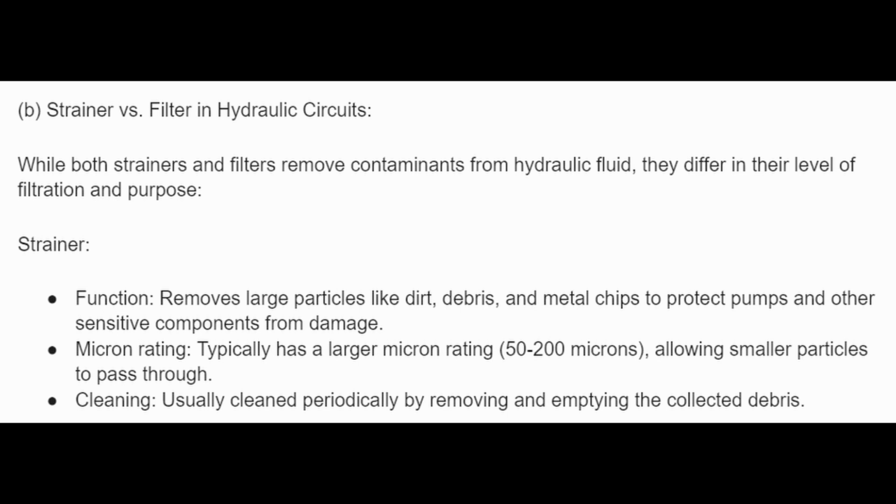B. Strainer versus filter in hydraulic circuits. While both strainers and filters remove contaminants from a hydraulic fluid, they differ in their level of filtration and purpose. A strainer. Its function is to remove large particles like dirt, debris, and metal chips to protect pumps and other sensitive components from damage.